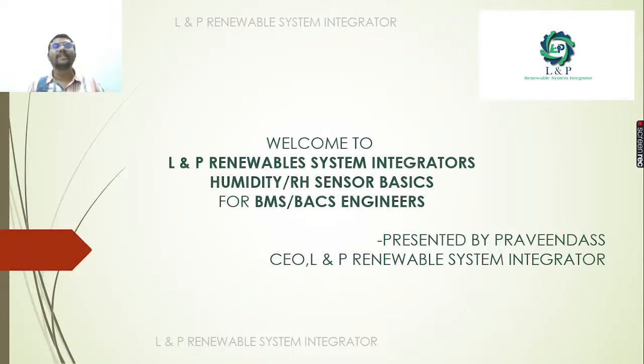Today we are going to discuss some of the basics of humidity sensors, or we can also call them RH sensors. If you're going to work in a building management system or a building automation system where you are using variable air volume units, air handling units, fan coil units, and even chillers, in such places you will come across sensors like the humidity sensor.